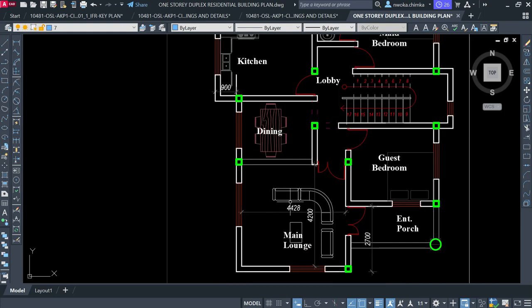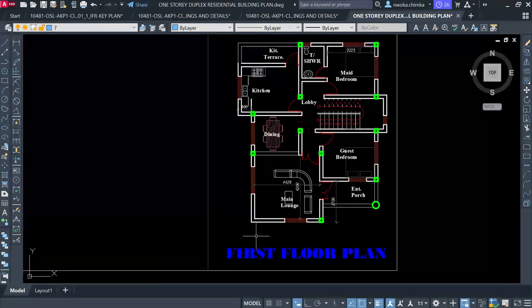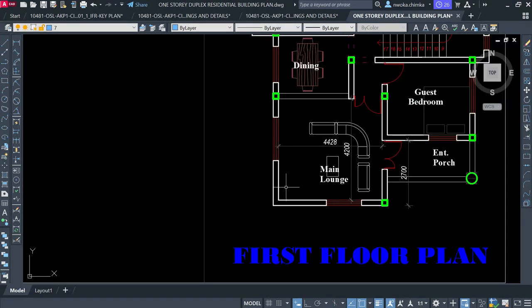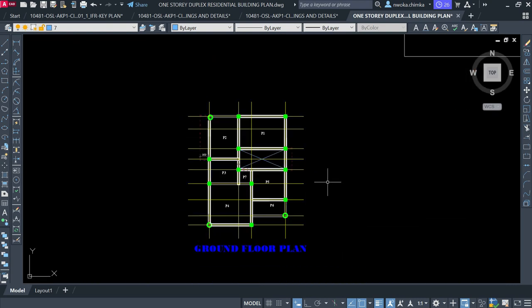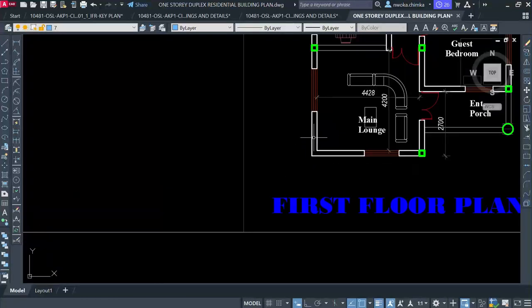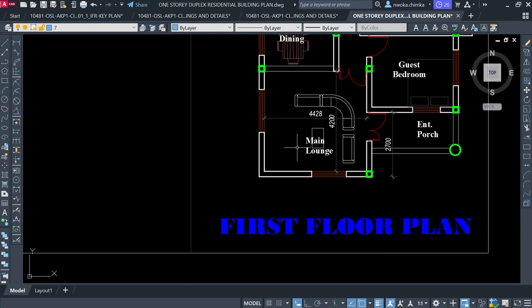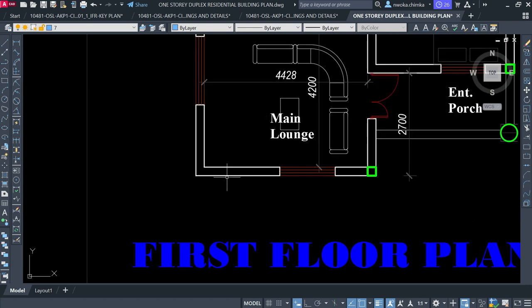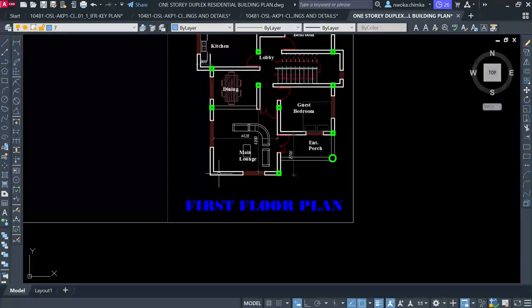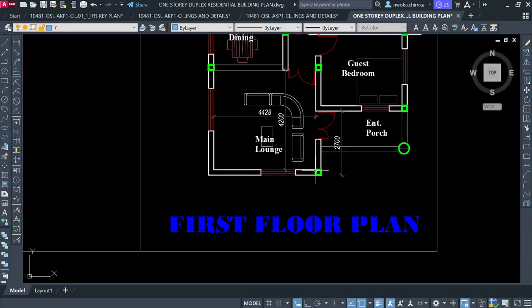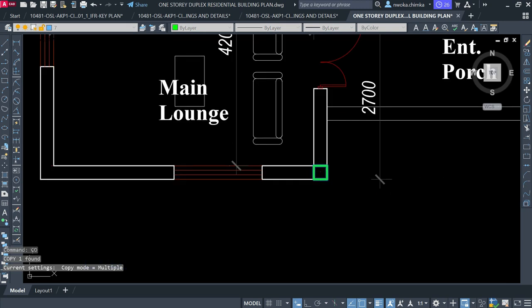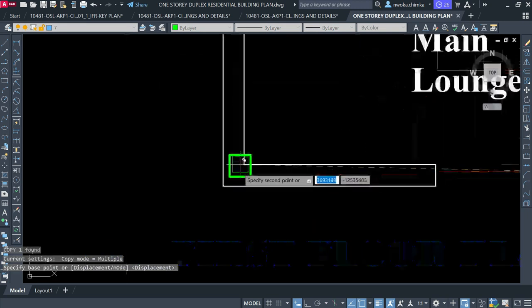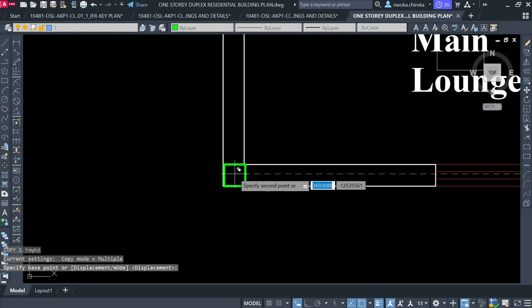Okay, now the next thing to do is, looking at this point on this first floor, knowing that this circular column is not going up to this place, the question will be, what will carry this beam at this place? And for you to cantilever this beam of 4 meters is not wise. So the next thing to do is that you are going to establish a column at this point when you insert on this story.